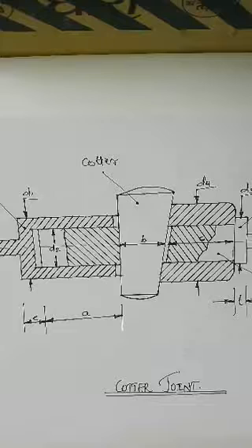Joints may be temporary or permanent. Most types are designed to be disassembled. Cotter or wedge passing through the hole fix the parts tightly together. The application of cotter joint is connection of piston rod with the cross heads, joining of tail rod with piston rod of a wet air pump, foundation bolt, connecting two halves of a flywheel. These are the most common applications for the cotter joint.